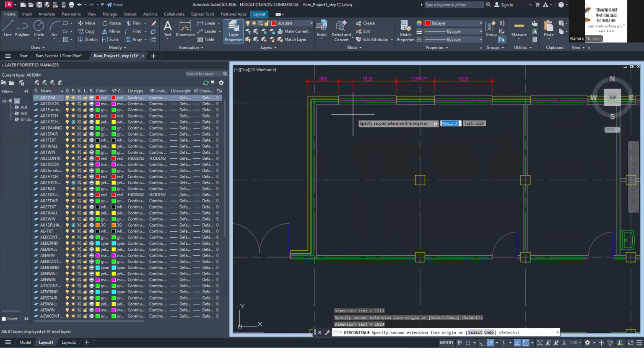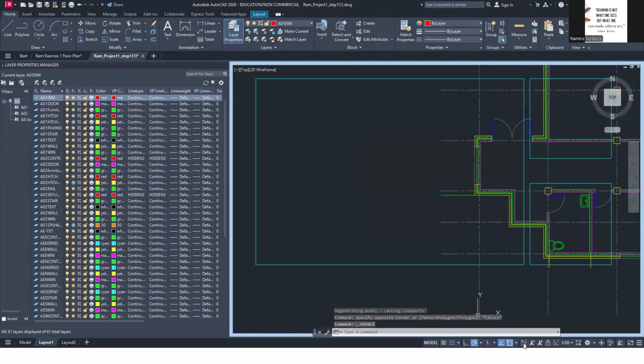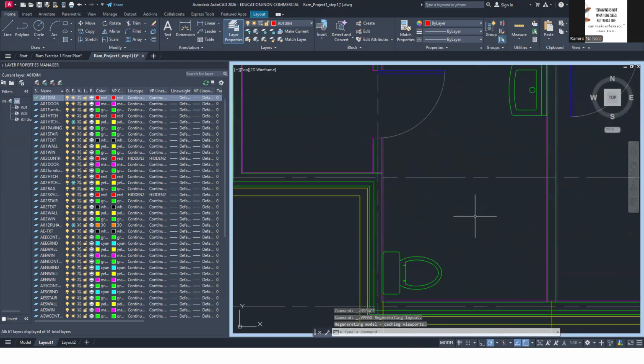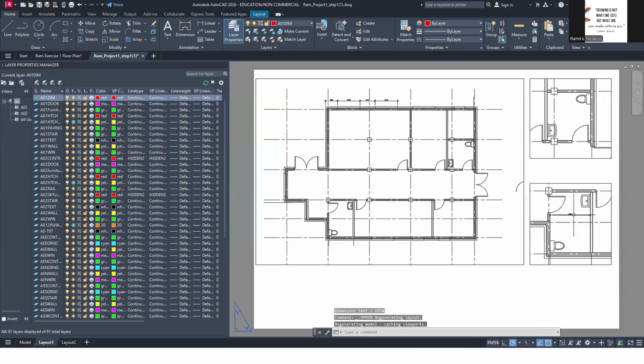Okay, and then make sure these two buttons are off. Minimize. It shows here. It shouldn't show there. Same here. Maximize. Zoom in. Dim linear. So let's just say I'm going to add a dimension here. Okay, it will show here, but not there. Okay, you add the text. So that will be for the project.